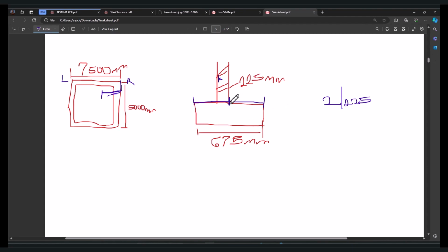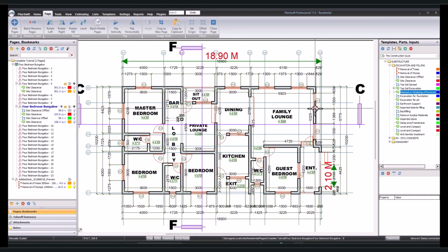So now I think we've explained this. So we have 2 of 225 to our length and 2 of 225 to our width. And if our thickness for our wall is 150, approximately this is going to be 450 as the thickness. And if we have 230 as our thickness here, this is going to be 690 mm. So whatever we have as our thickness of the wall is going to be our spread moving forward. So now that we have 225 as the thickness of our wall, we'll be adding spread of 225 around the perimeter of the building since we are using this software.